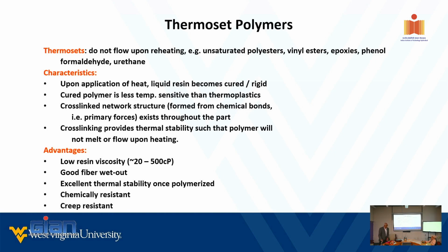Okay, go ahead, please. Just a quick question. When we talk to the manufacturers of GFRP bars, they say that the pulling speed, if they use a vinyl ester, is much faster. So they're able to produce the bars in a faster manner compared to when they use epoxy. But we know that from a durability point of view, epoxy slightly performs better, at least that's my understanding. Right, that's correct. So how different is it in terms of long-term performance between vinyl ester and epoxy? Is there any other reason the manufacturers prefer vinyl ester?